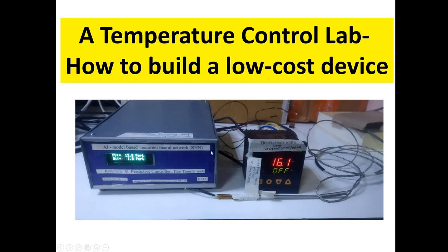That means the value which is here will be read here. Here you can see it is now called a process variable, PV, and it is 15.8. It is not percent, it is 15.8 degrees. And 0 to 100 degrees will correspond to 0 to 100 percentage.